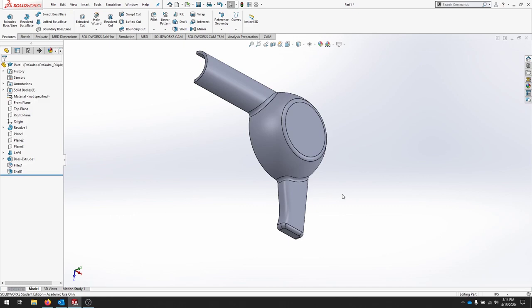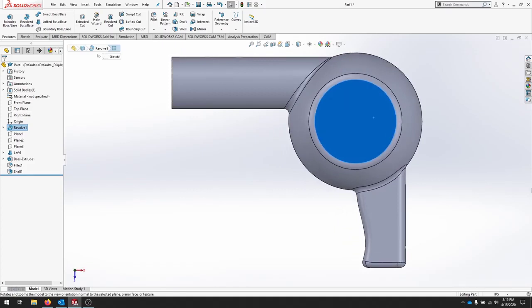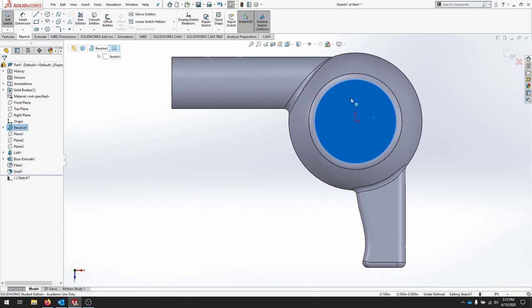Our next step is to create all of the vents for our blow dryer. In order to do that, we'll create a linear pattern, and then we'll repeat that over the geometry. All right, we'll select this face here, and then the toolbar that pops up, click normal 2. From here, we're going to create a rectangle that's going to be patterned over this face.